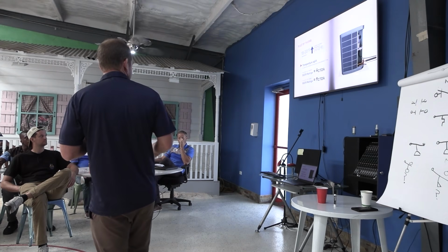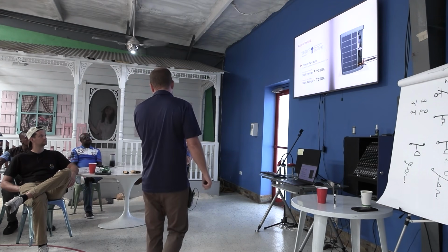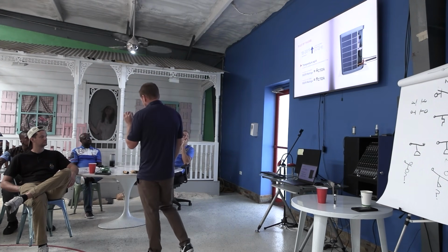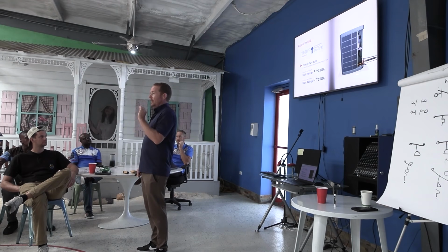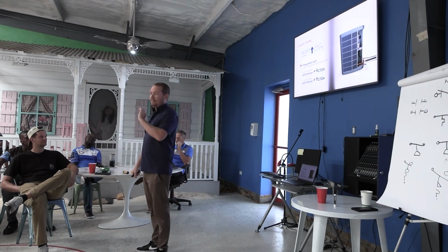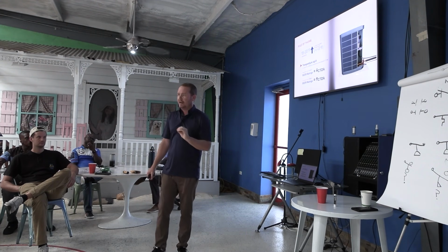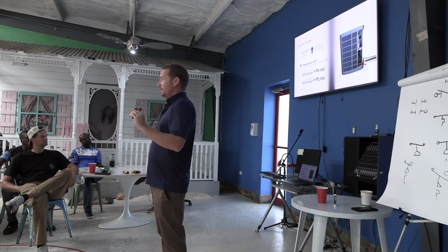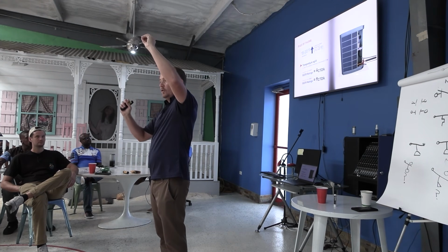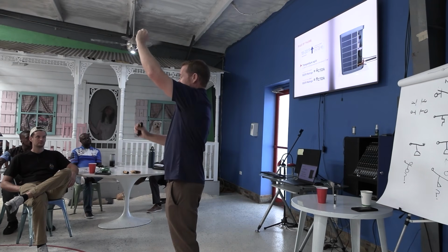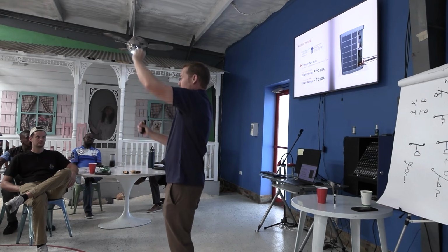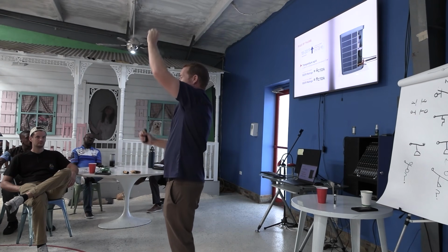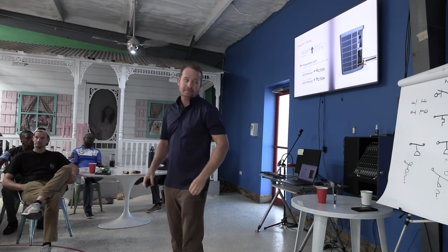I'm going to pause quickly and talk about one of my favorite topics, which is compression ratio. That's a fancy term. I'm not even going to tell you how to do the math because it does not matter to me right now. But here's what you need to know. When your head pressure is high or your suction pressure is low, see, low and high, see how they get further away from each other? That is a higher compression ratio, right?